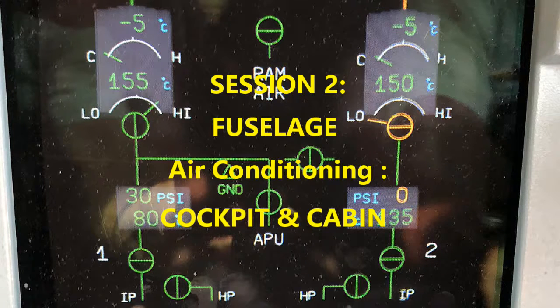There's also arrows on the fan casing that show the direction of the airflow through the fan and the direction that the impellers are rotating. So there are those markings. You also have overheat thermo switches. You also have, on the overhead ventilation panel, the cab fan's push button switch in the cockpit, and that switch is supplying electrical power through the circuit breakers to the relays in order to move those fans.